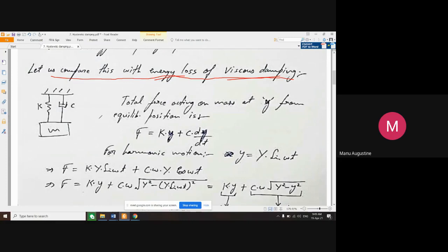First, let us forget about hysteretic damping. We are coming back to viscous damping. And in this case, we are going to find out how can I model the energy lost per unit volume, per cycle of the vibrating or oscillating system. So this is our standard model for a system which has viscous damping. So you have a damper here, you have a spring to represent the elastic components of your system, and M represents the weight or the bulk of the moving parts.